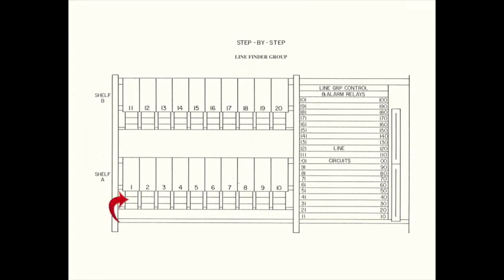So the 200 tip, ring and sleeve terminals on bank 1 are multipled to bank 2, which are multipled to bank 3, and so on down to bank number 10. That multiple then is carried up to the upper shelf and multipled from bank 11 to bank 20.